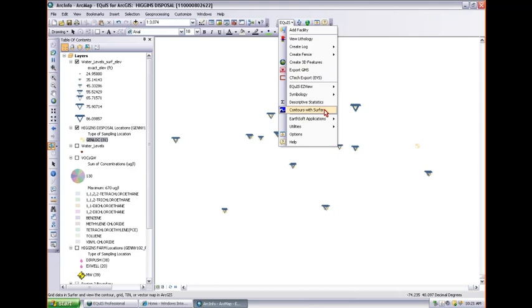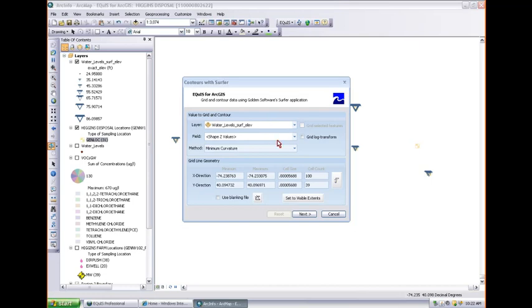You can also use the ESRI Spatial Analyst or 3D Analyst to do contouring. If there's a request, we could walk through that. But I think you'll find that the contours with Surfer give you the best quality, the kinds of contours you expect in engineering drawings. The ESRI ones are kind of jaggy sometimes, with staircase effects that I wouldn't put in a report. Again, we try to mask Surfer for you, so you just learn our interface, and then if you wanted to be advanced, you can choose to modify it in Surfer before we come back into the GIS.